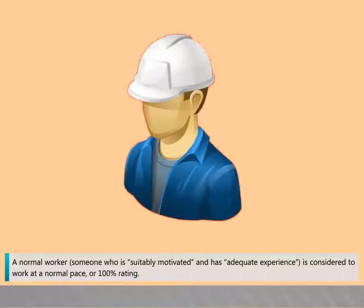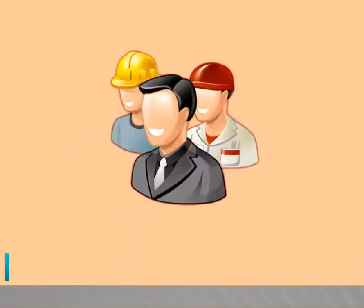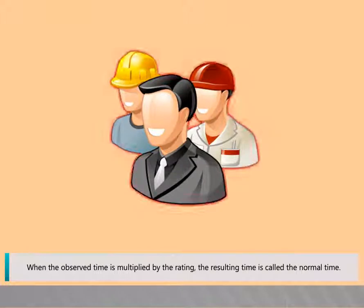A normal worker, that is someone who is suitably motivated and has adequate experience, is considered to work at a normal pace or 100% rating. This allows for a longer normal time if the observed worker is working faster, and shorter normal time if the observed worker is working slower than a normal worker. When the observed time is multiplied by the rating, the resulting time is called the normal time.